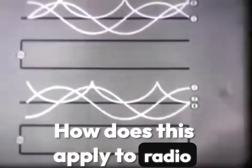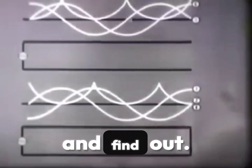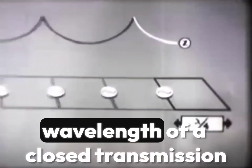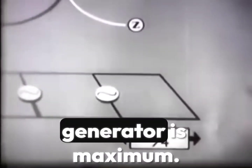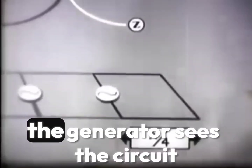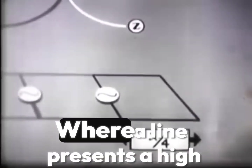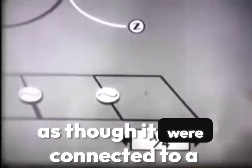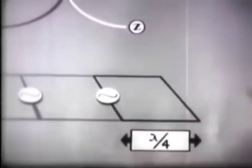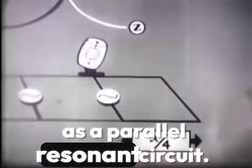How does this apply to radio antennas? Well, let's shorten our closed-end line and find out. Now we're working with only a 1/4 wavelength of a closed transmission line. The impedance at the terminals of the generator is maximum. In other words, the generator sees the circuit as one of maximum impedance. Where a line presents a high impedance to the generator, it is the same to the generator as though it were connected to a parallel resonant circuit. So we can symbolize this 1/4 wavelength line as a parallel resonant circuit.